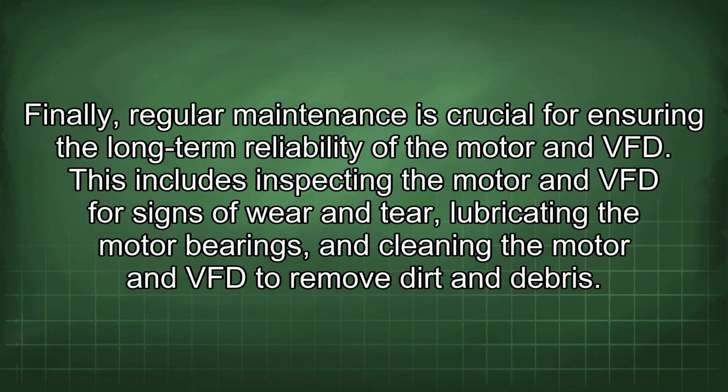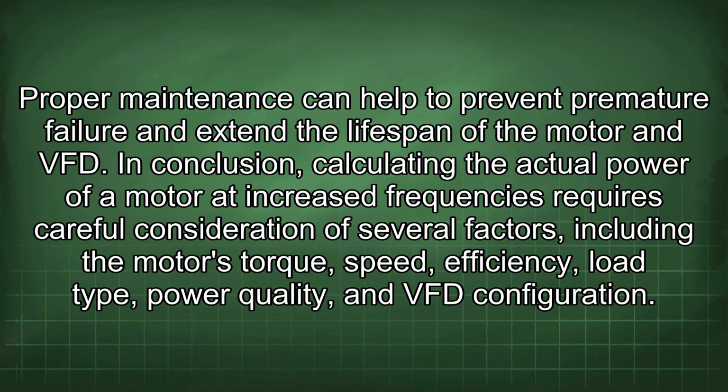Finally, regular maintenance is crucial for ensuring the long-term reliability of the motor and VFD. This includes inspecting the motor and VFD for signs of wear and tear, lubricating the motor bearings, and cleaning the motor and VFD to remove dirt and debris. Proper maintenance can help to prevent premature failure and extend the lifespan of the motor and VFD.